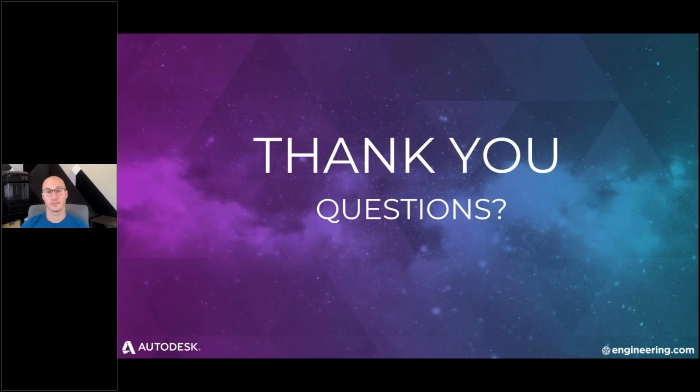Awesome, thank you. How do you control the resolution of the mesh? Great question. So when you're converting from a solid to a mesh, you're going to have the option to choose the resolution. There's actually a whole lot of options when you're tessellating a solid body to choose the resolution. Once you have a mesh, if you would like to re-tessellate the mesh or remesh the mesh, you can do that as well. And in those features, there are options to be able to do so.